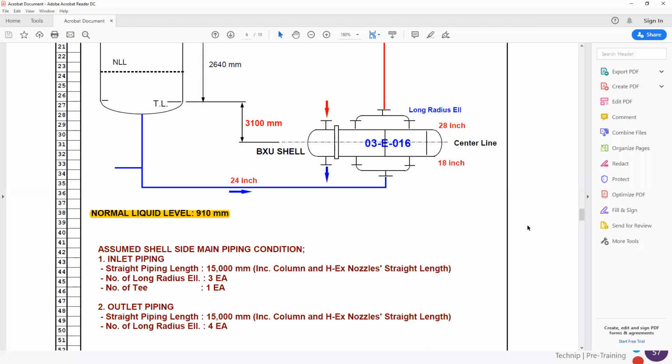Having this process constraint doesn't mean that we say, no, it is better for the design of the thermosiphon that the most fouling fluid goes inside the tubes. No, because we can work with it and we can place the fouling fluid on the shell side, but we are going to leave my exchanger ready for maintenance.